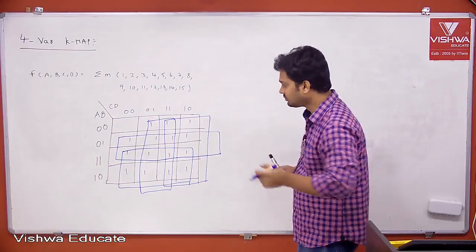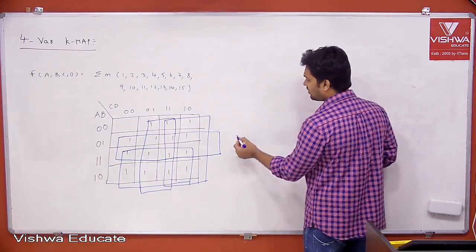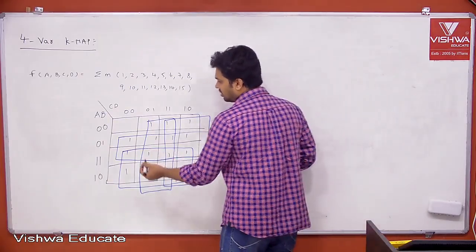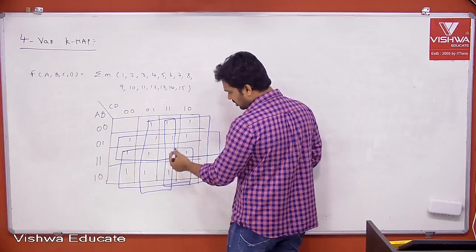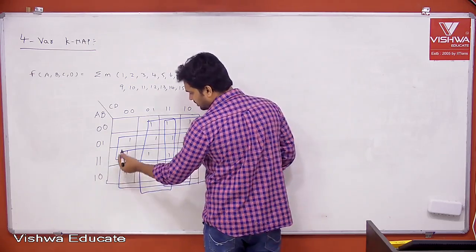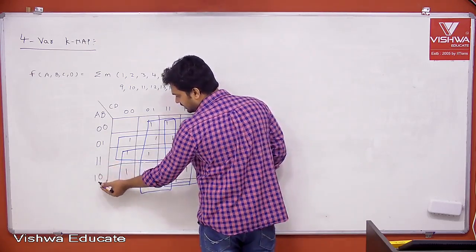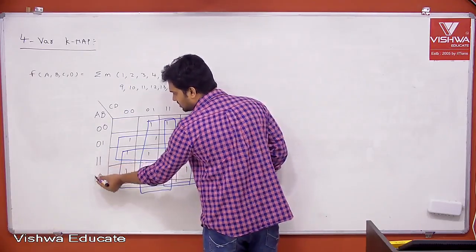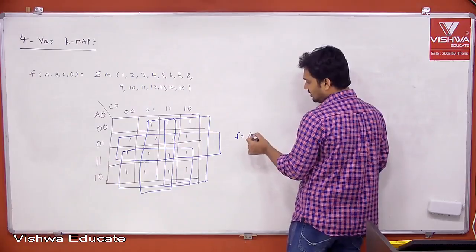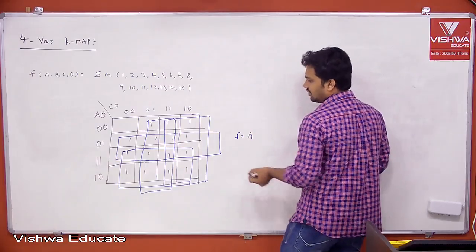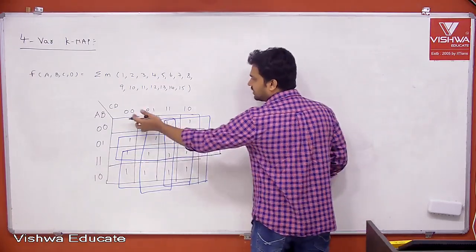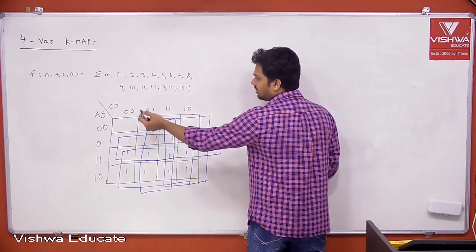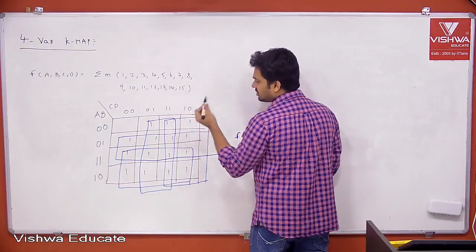Okay. So let us write the expression for this. F equal to, what is F? Starting from the bottom octet. What about this octet? In this octet, here first and next, in these two, what is common? 1 is common. 1 means here A. In this row, nothing is common. You observe, you add all this, it will get 1. That is C bar D bar plus C bar D plus CD plus CD bar.